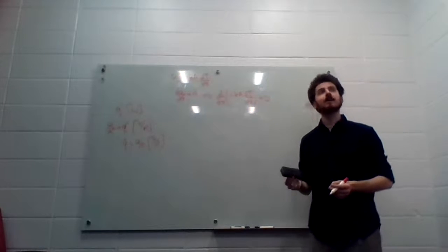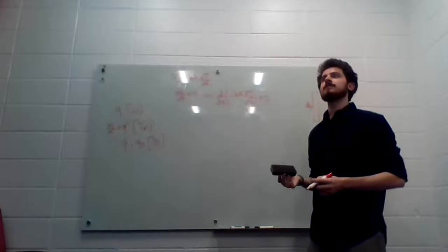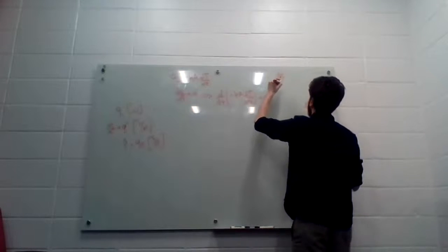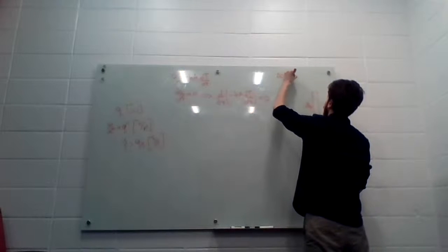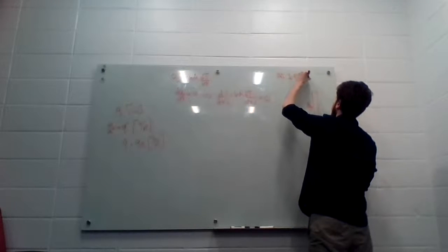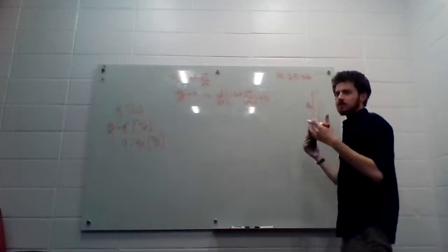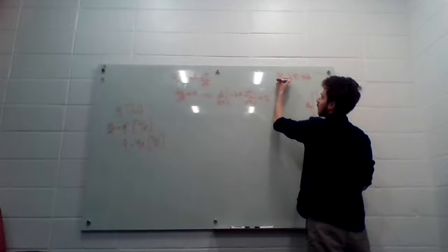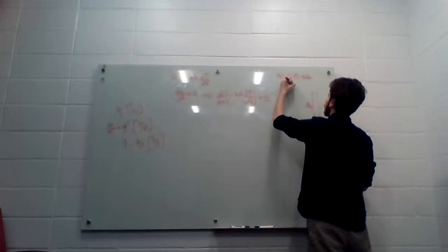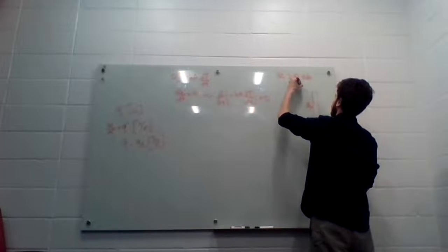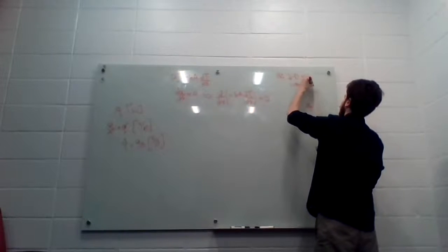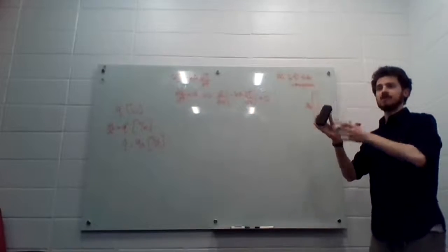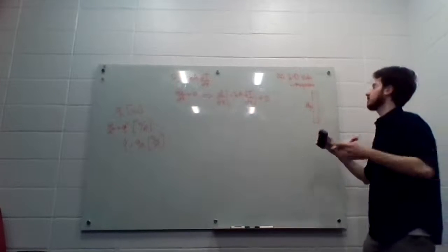And then K not changing with X is a good assumption for a homogeneous material. So our assumptions are 1D slab. And typically when you say slab and heat transfer, that's what people picture, a flat surface. And then the other one I said was homogeneous material. So this would only apply to a single material, so it would apply to the fiberglass in a wall, but it won't apply to the fiberglass on the concrete and all that stuff because those things do change.